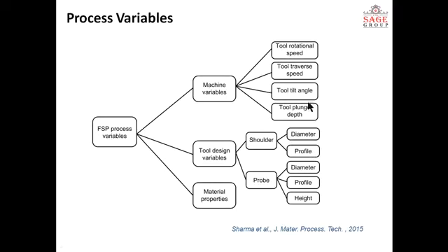In the diameter, the more the diameter, the more the contact, and the more the heat will be generated, but we have to spend more power on it. And the probe: probe diameter, probe profile, and probe height. When probe diameter increases, it will consume more power. And the profile, we have to select wisely which profile can be used,